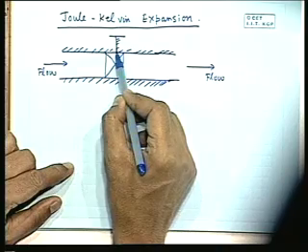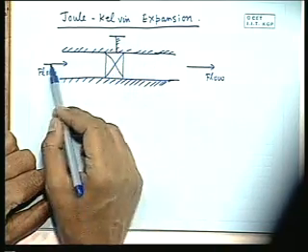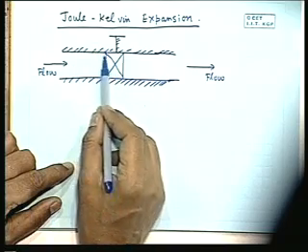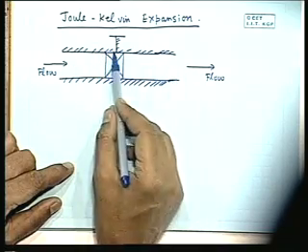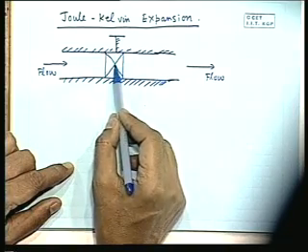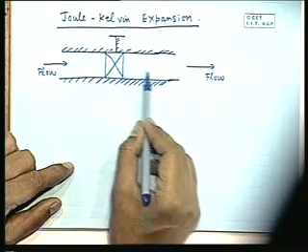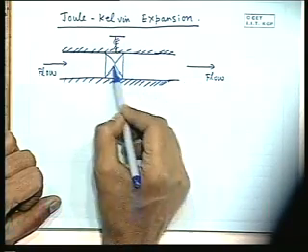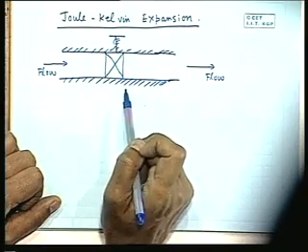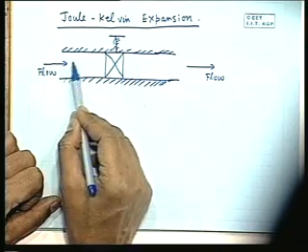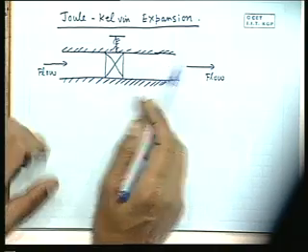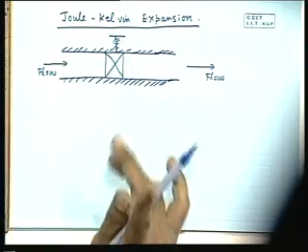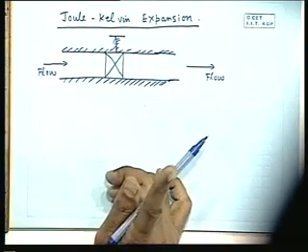If the valve is completely closed, then the passage is completely closed and the flow cannot come through. So this becomes a static condition: the flow comes here, strikes here and exerts a pressure, but there will be no flow beyond. As you gradually open the valve, that means allow the flow to take place through restricted passages, the flow starts taking place. Now in such a condition of partial opening or partial closure of the valve, when the fluid flows through the valve and some flow is maintained at steady state, then we know that the pressure across this valve drops. That means there is a sudden decrease of pressure across the valve.